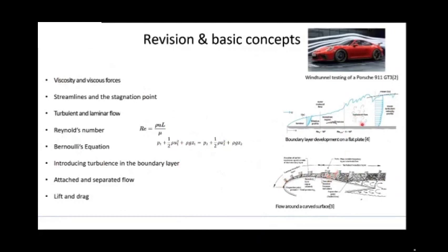And you can see as we increase the turbulent flow, we've got this vertical motion. We increase the height of our boundary layer. And if we're increasing the turbulence earlier due to the mechanisms that I'll be talking about in this presentation, we're drawing down kinetic energy from outside of our boundary layer into our boundary layer.